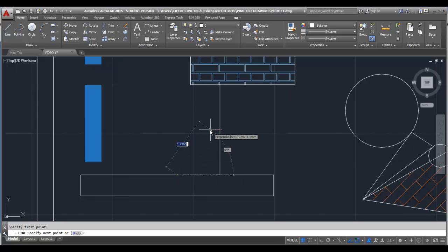When I see this and start pulling it back, you're going to see this green line show up. And then when I get back to this point, it's going to lock in. So it tells me that I'm halfway up to that line, I'm perpendicular, and I can just left click and go back over here and put a point right into that center point. And it's going to be absolutely straight and level. We don't always want straight horizontal and vertical lines, but it's nice to know that you have those snap abilities just to speed up your process.